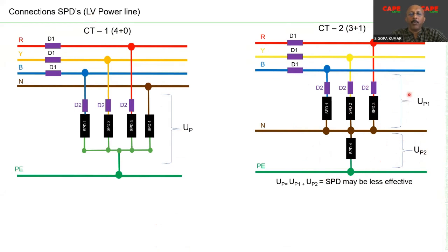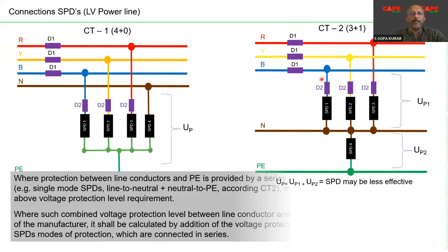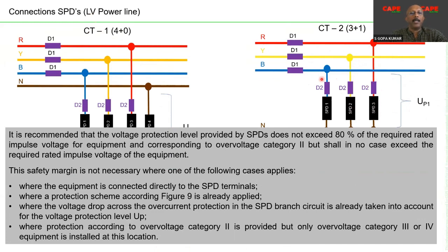So say, for example, 1.5 kV in the first case where I am moving the cursor plus 1.5 kV in the second case. So the effective protection level of both the SPDs itself will be about 3 kV plus the voltage drop of the connecting wire. So basically there is a risky situation if you don't select the correct SPD.